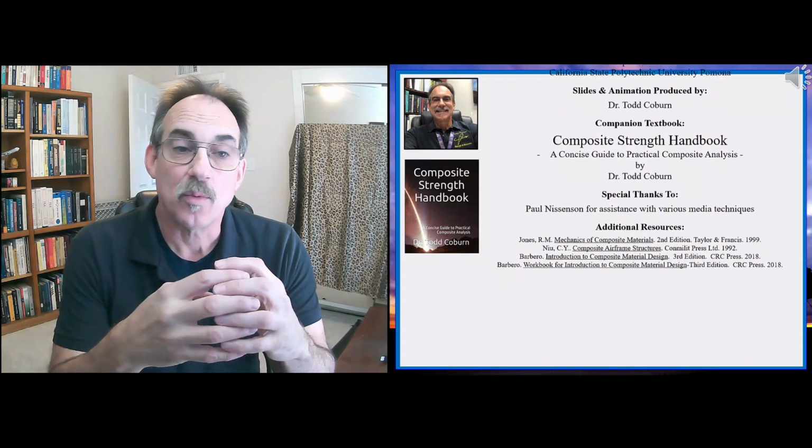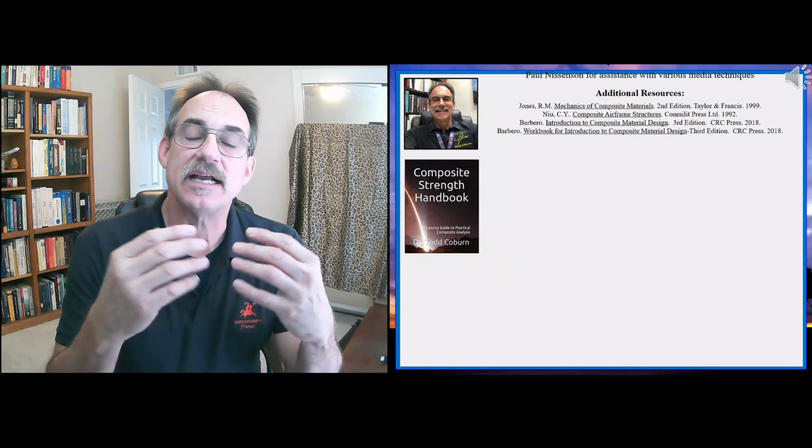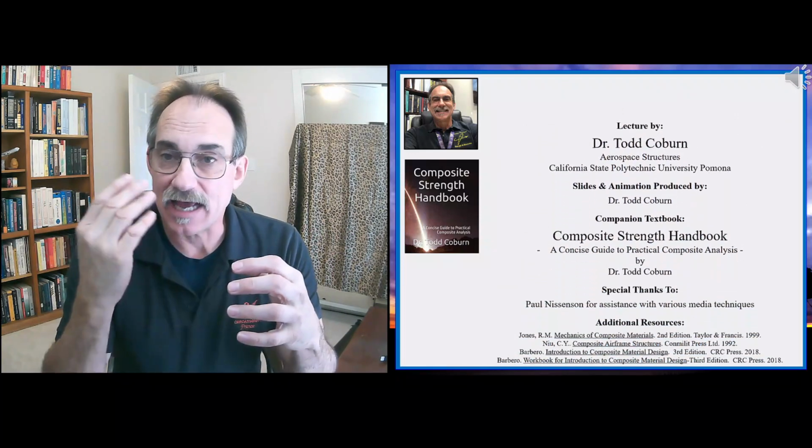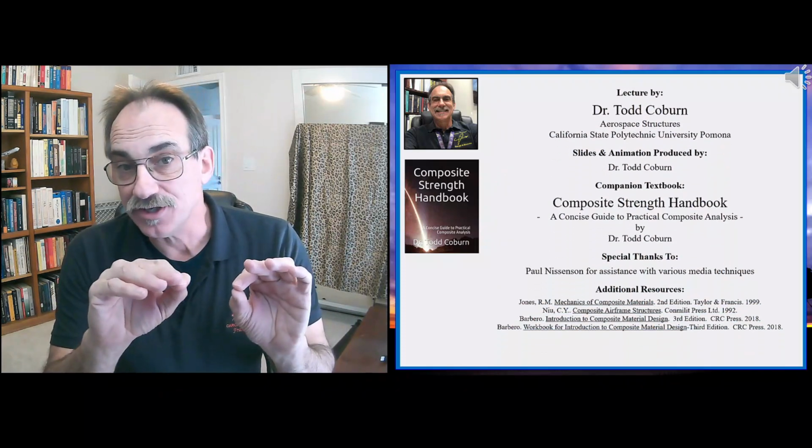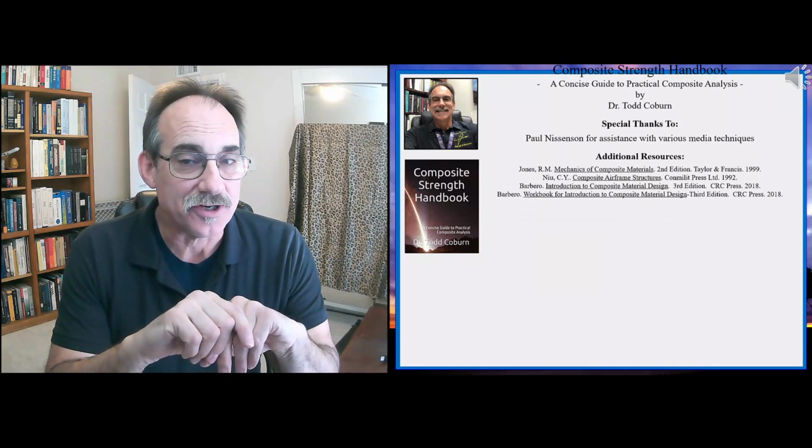So that is how we do testing of composites. You're going to want to get a hold of those ASTMs to read through those. There's a lot of material, but I have here something to make it a little easier to get your feel for what it is you're trying to do, and then go to the ASTM to get the precise dimensions and load rates and equations for your particular application.